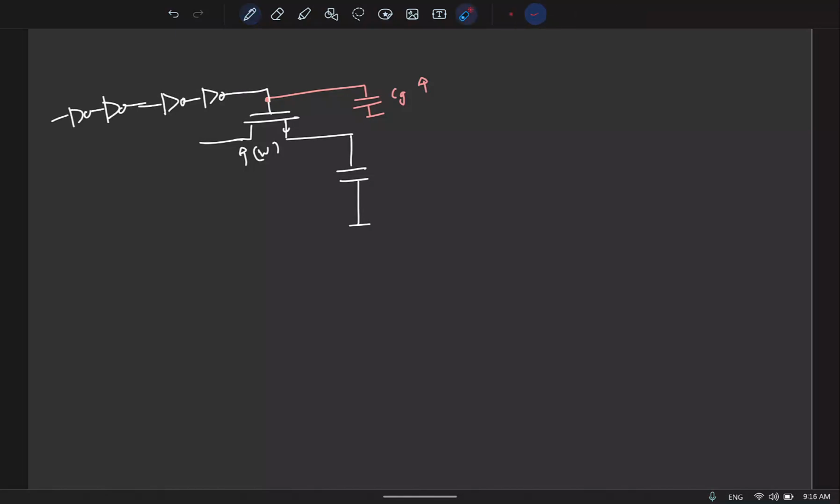and the moment you increase the capacitor, to make sure that the clock is also rising fast enough, you have to make the inverter stronger. If you have a CMOS inverter driving a load and the load capacitor increases, you have to increase the sizes of these devices, which means they will consume more power. At any point, if the load capacitance increases or the load resistance decreases, the main issue is that the stage driving this load will have to consume more and more power.